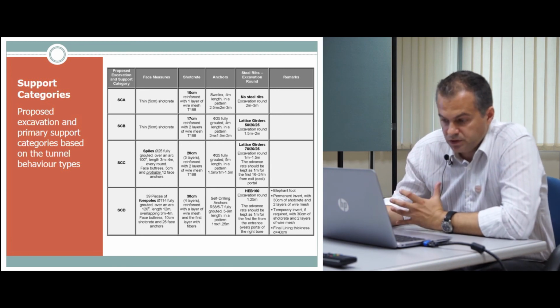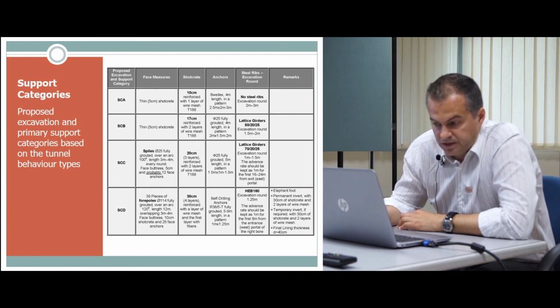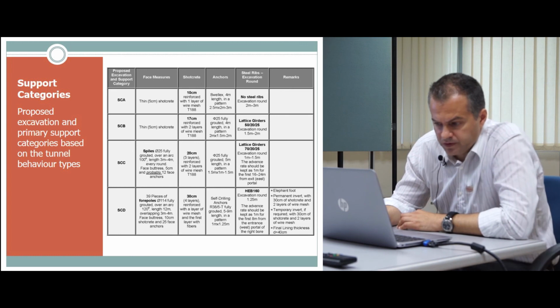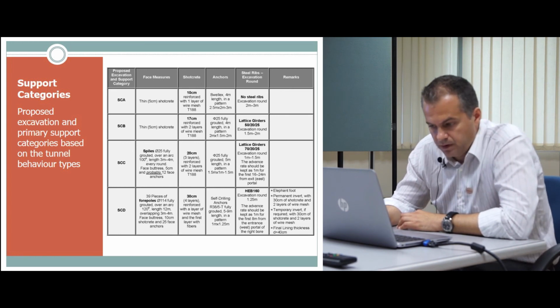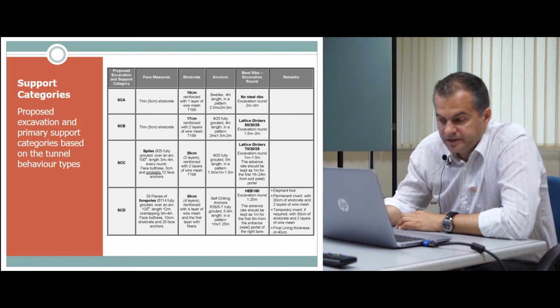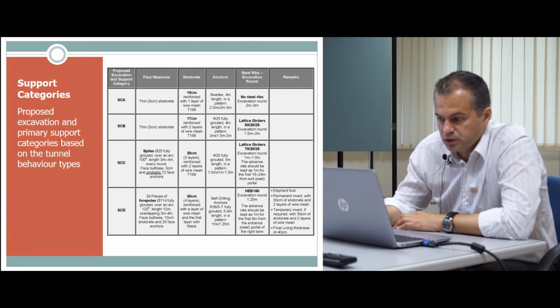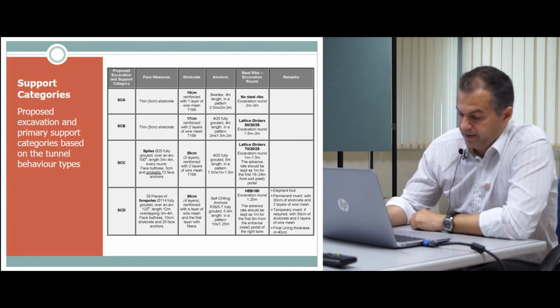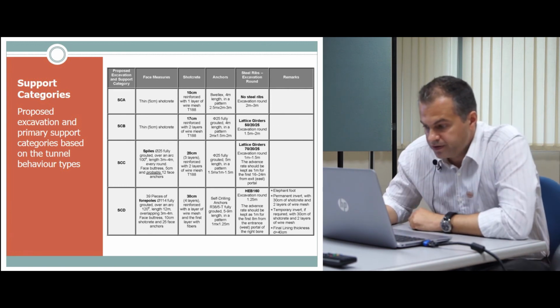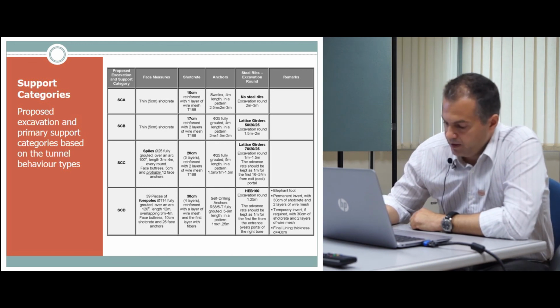The large one, which is shear strain failure and isotropic failure of the rock mass, here you need some spiles, face buttress of shotcrete and face anchors to keep your face safe, and thick shotcrete, a more dense pattern of anchors, and heavy steel sets are required here with elephant foot, and a permanent invert may be required for this kind of ground conditions.